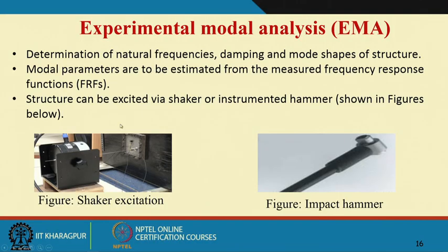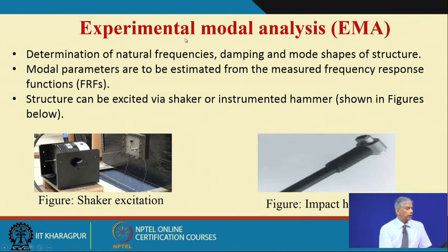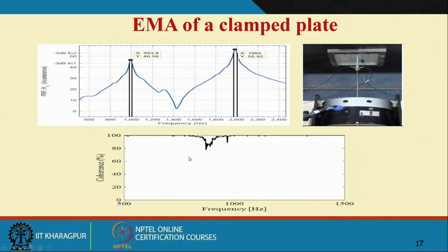Of course, I have shown you impedance and mobility. Sometimes, to know more about the systems, there is a technique called experimental modal analysis. We will be discussing this later towards the end of this course, but just to give an example, here we have a plate and a transducer is put to measure its response. This is an exciter, or I could have an impact hammer with a force transducer. So, simultaneously I can know the force being applied to the system and the response generated. Then I can find out the impedance or the mobility of the system and plot it as a Bode plot to find out the natural frequency.